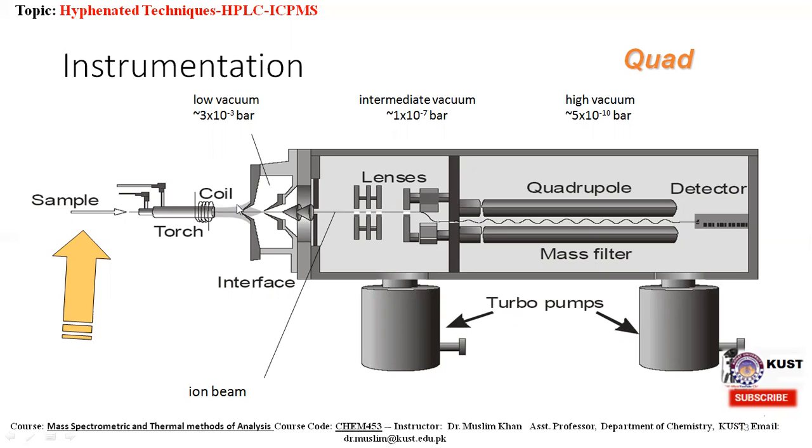The fine droplets of the aerosol, which represent only 1 to 2% of the sample, are separated from larger drops by means of a spray chamber. The fine aerosol then emerges from the exit tube of the spray chamber and is transported into the plasma torch